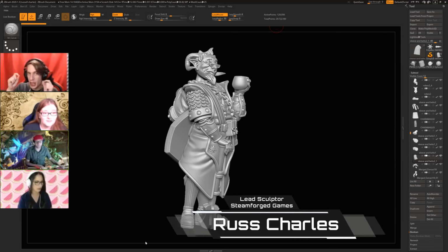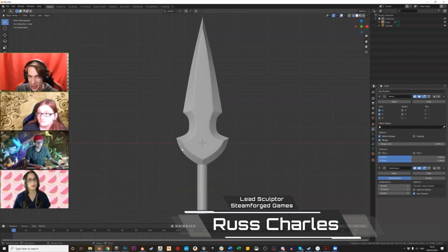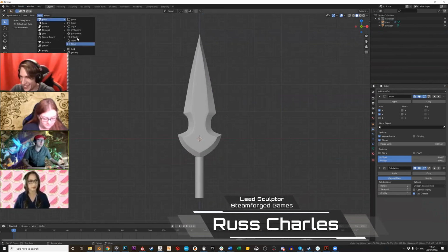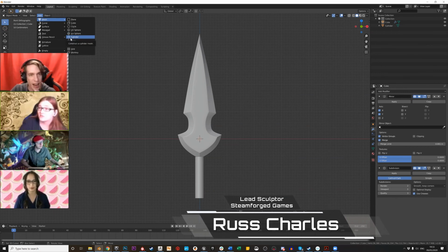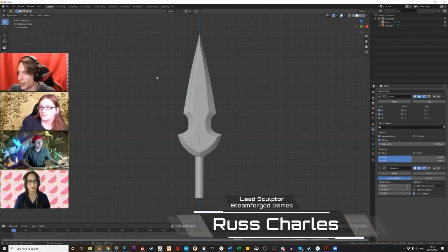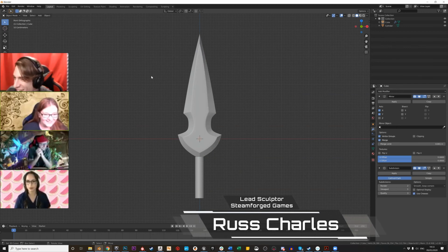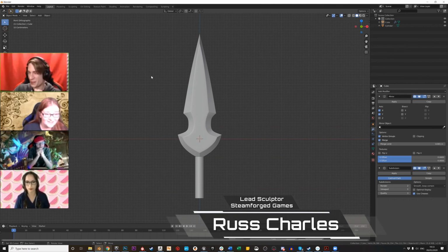There's got to be like one button to make a big cylinder in Blender, right? There is. It is Add, Mesh, Cylinder. Yeah, you've got to be in object mode. You need to hit Tab to come out of edit mode. And luckily, Add, Mesh, Cylinder.